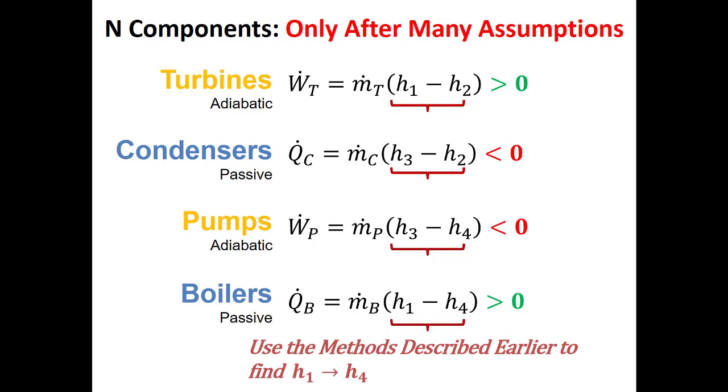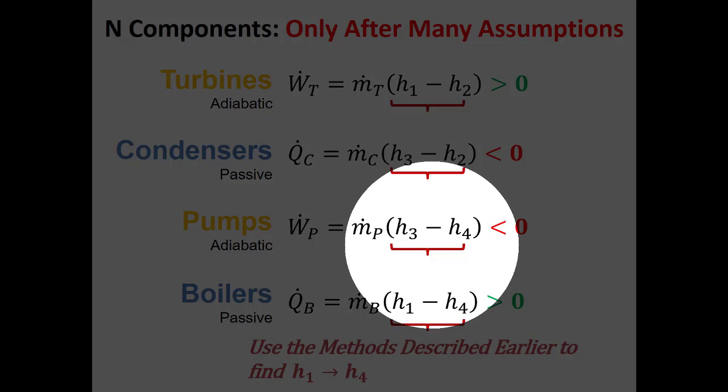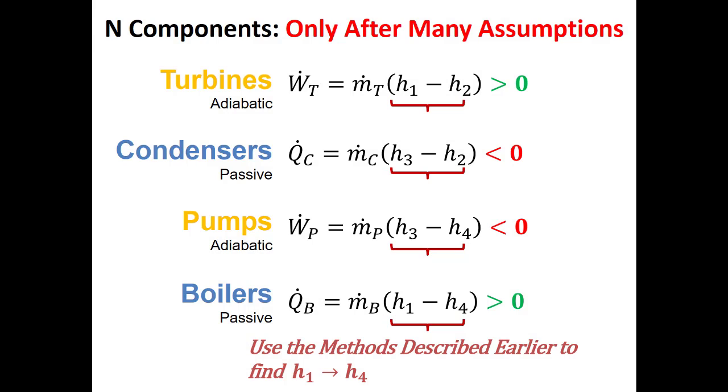It's a Rankine cycle, so when you ask what's the fluid, it's the same as a basic Rankine cycle, and you're just going to use the same processes. Again, I think the trickiest part here is for the pump. If it's an isentropic pump, you'll have to remember that delta h is v times delta P.